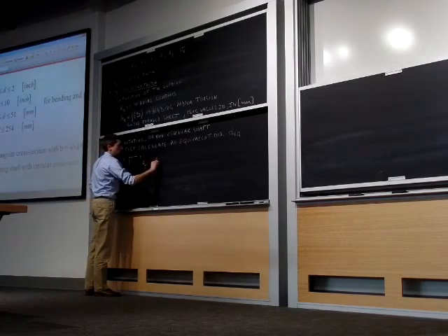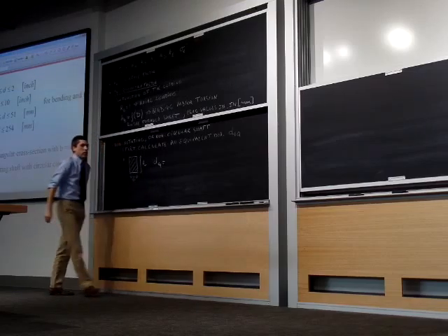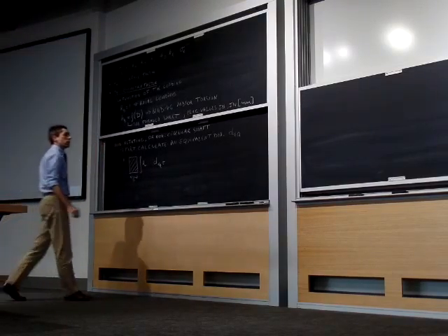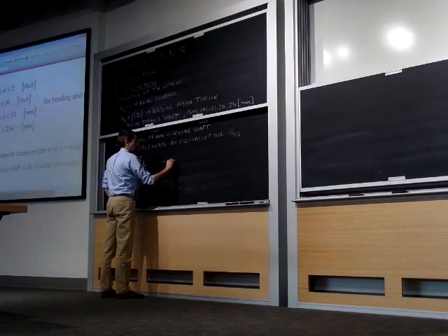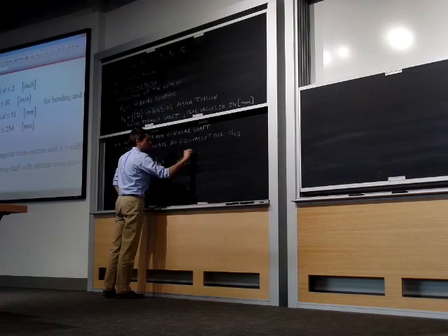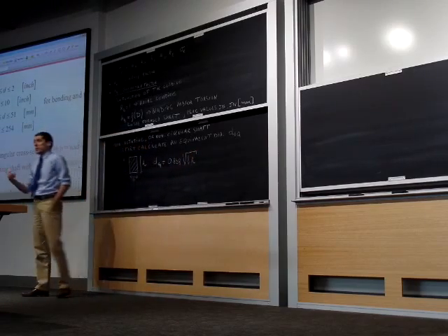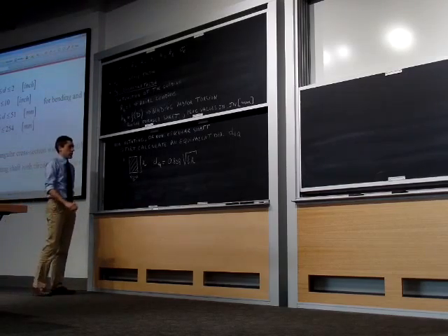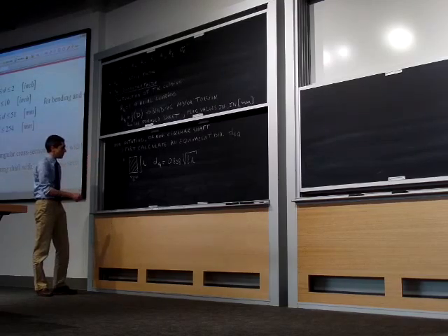Then our d equivalent is given as, and it's in the formula sheet there, 0.808 times the square root of b times h. Of course, that also works for square cross-sections, right? Just set your b equal to h, and then your equivalent diameter is going to be 0.808 times the side of your square.